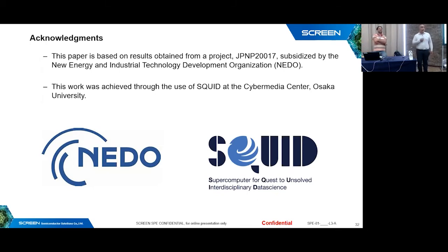Yes. Thank you for the talk. Very cool simulations. I'm a little bit confused about this RANS and LES thing. So with LES, do you actually resolve the turbulence then? I realized you got bad results for the RANS, and then got better results for LES, and then it's on the same grid. But I'm a bit confused. So what changed, so to speak? I mean, did you actually change the turbulence modeling regime? Did you have fluctuations in the LES, let's say?